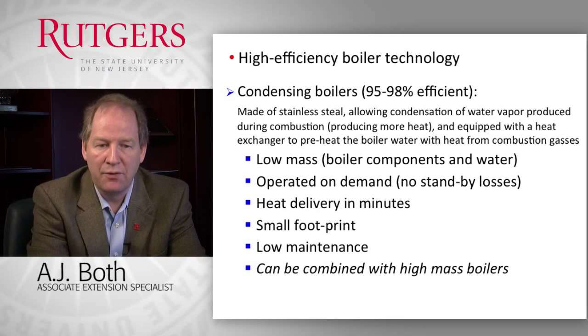There's a new class of boiler technology that I think is very interesting, and it typically generates much higher conversion efficiencies than conventional boiler systems. They include the condensing boilers. Think about the combustion process. The combustion process generates typically, if it works well, carbon dioxide as well as water vapor. And it requires energy to generate that water vapor. And that energy is typically lost when we expel the combustion gases to the outside environment.